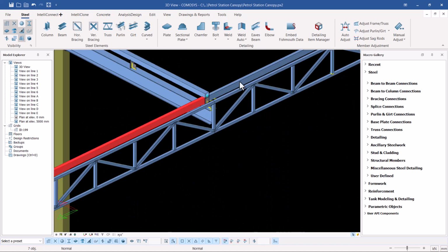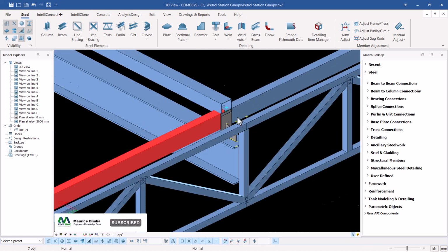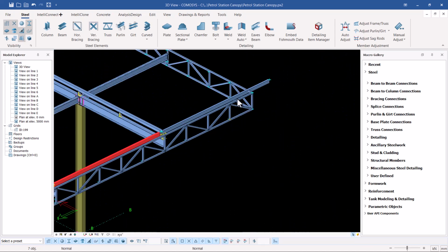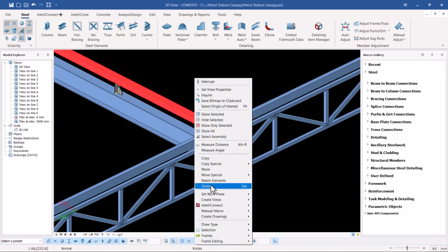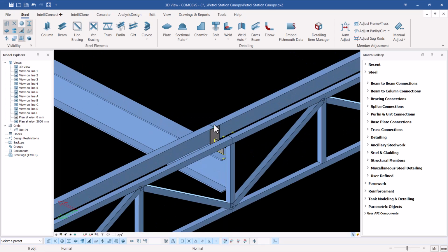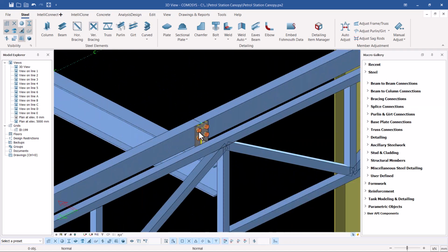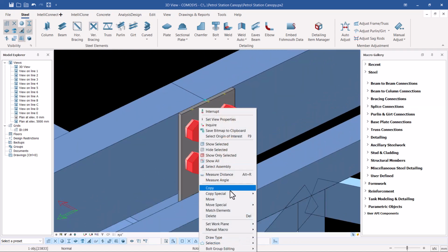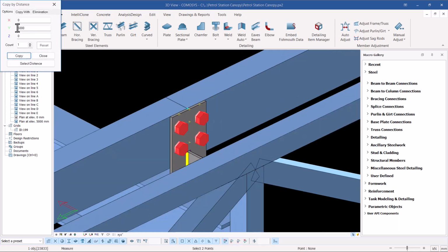We can leave this behind because we don't want to do repeated work, since this is already overlapping, and we don't want to copy it and start modifying every error we've created. So let me copy this, right click, come to Special copy, come to Linear, and feed in a negative sign there to show a different direction we're heading to, and click Copy.